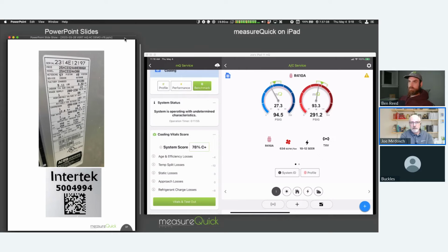I encourage you to make sure that if you don't think it's an issue in the system, then you need to check your probes. Sometimes your probes are in the wrong location or they weren't inside the supply register. All of these things allow us to generate that.